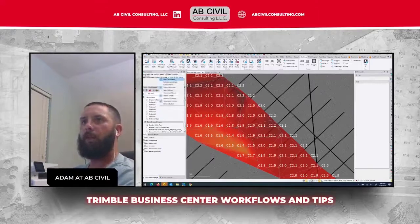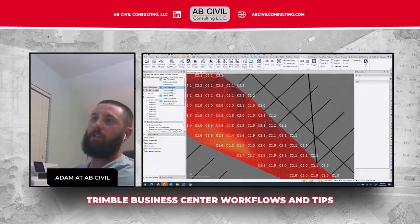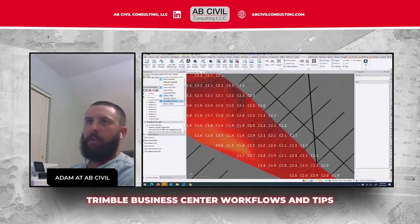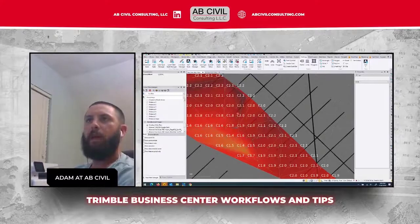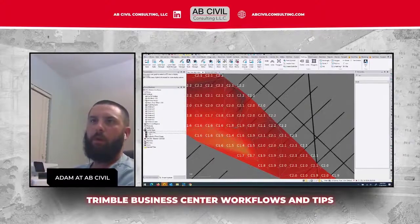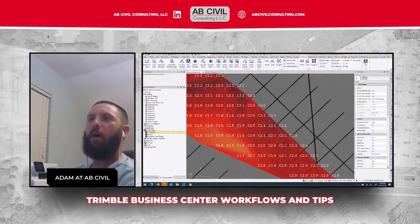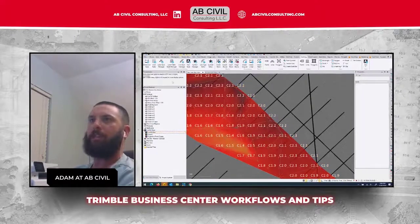If you right click in there, these are all the options that your cursor will read out as it's scrolling. It'll give you the surface elevation of the most recently selected surface. If you have an alignment, station offset, there's a lot of different things. Grid coordinates, not very useful most of the time. So I'm going to do surface elevation. And the way to get this to work correctly is you go to Project Explorer. In this case, I think all I have to do is click Cut Fill Map, and then I can click out. And now it's registered that as the last surface.